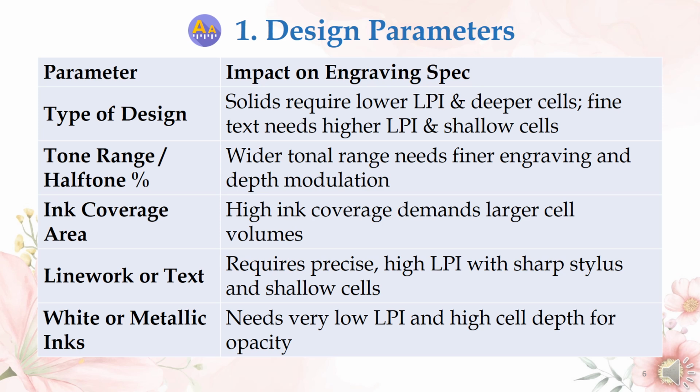High ink coverage demands larger cell volumes. Line work or text requires precise high LPI with sharp stylus and shallow cells. White or metallic ink needs very low LPI and high cell depth for opacity.